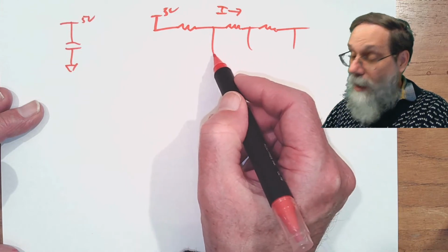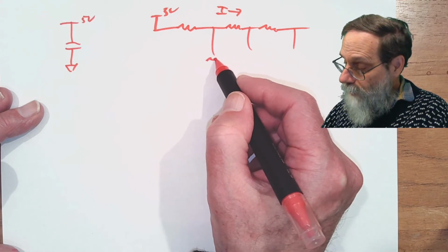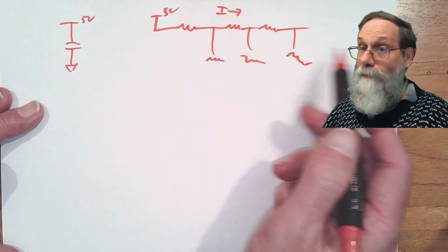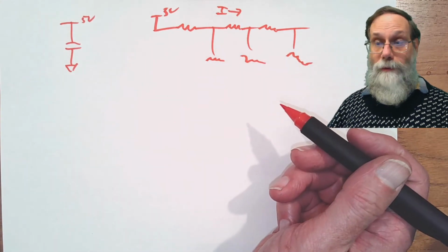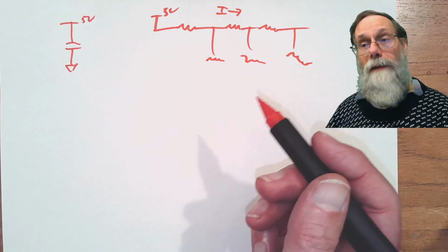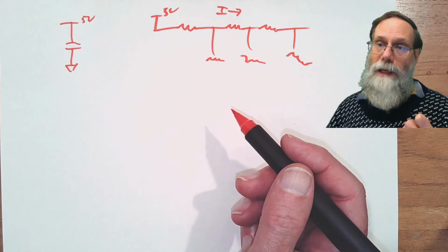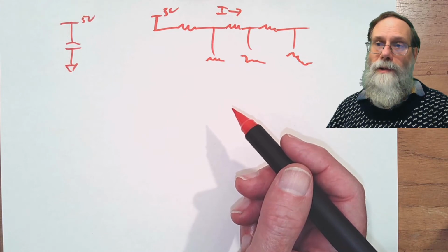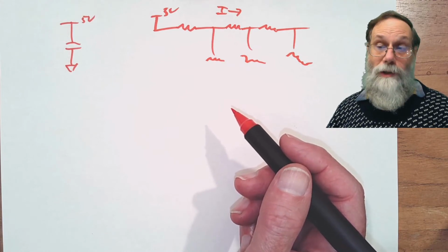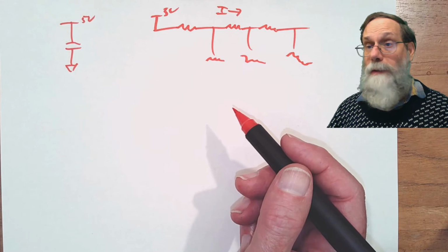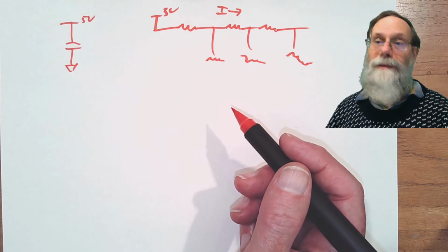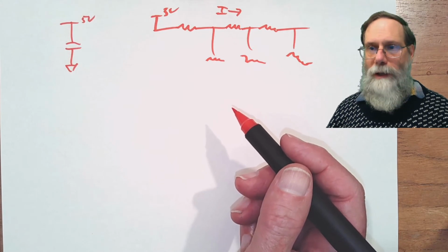And instead of having a constant voltage here, you're going to have a fluctuating voltage. And the fluctuating voltage may not even be the same in the different places you're looking at the wire. So instead of the 5-volt thing really being a node, you may have to think about it as a bunch of resistance. And if you're working on some high-speed stuff, you may even have to worry about the inductance of the wiring.